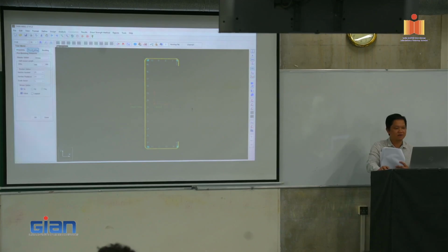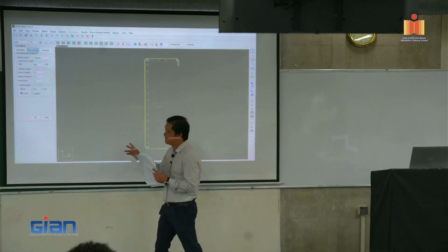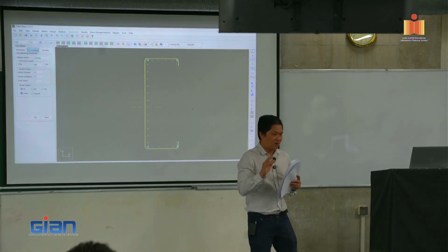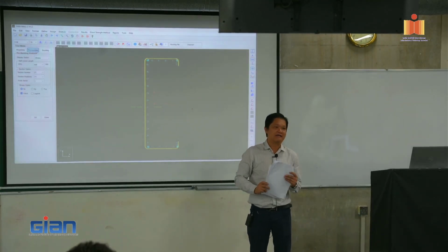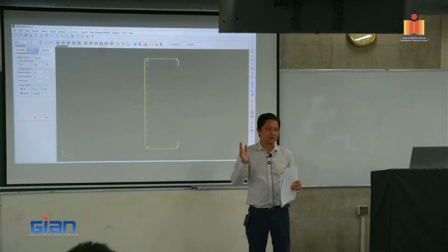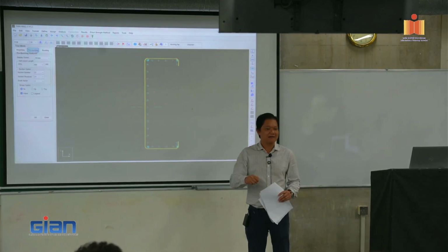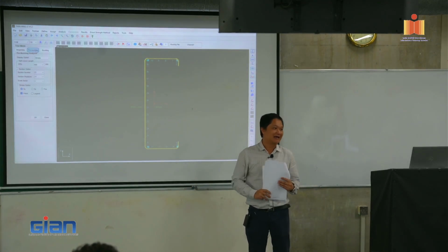So I can see here, that's the result on your right. You can click on pre-buckling and buckling, okay? The reason why we have pre-buckling analysis and buckling analysis is because it's all for localized loading. For uniform loading, you don't have to worry about that because the stress is distributed constantly along the member. It doesn't matter. So you just put straight away the stress in the member and run buckling analysis.